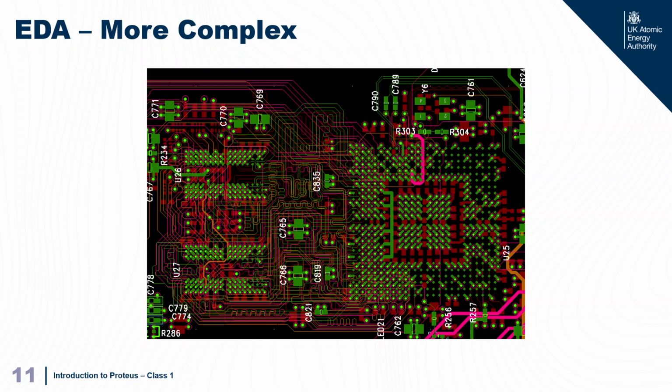You've got like orange, green, pink, red. They've got a load of vias on there as well. Now, a via is a tiny little hole drilled through the circuit board, and then it's got a tiny little plated barrel. So vias connect layers together. You need some way to connect layer 1 to layer 4. That's the way that you do it.